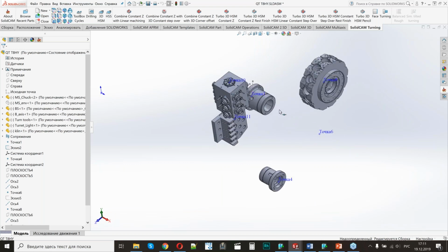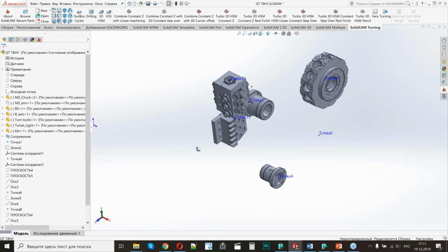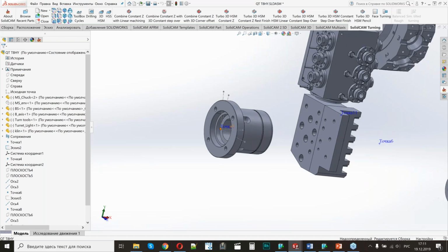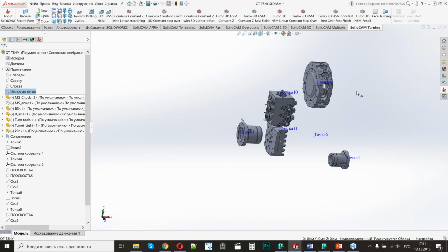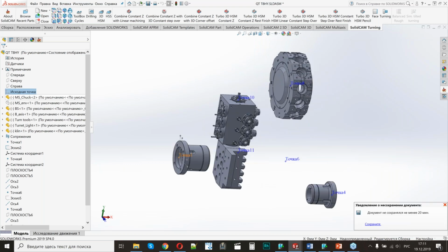Now we will think about the spindles of the machine. I will start to define the machine ID from the main spindle and the 0 assembly point. As you can see, it is here. This is my assembly point of the machine, for the machine ID file and for the 3D assembly. And I should put it into the machine ID file.